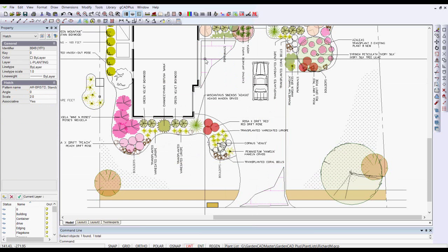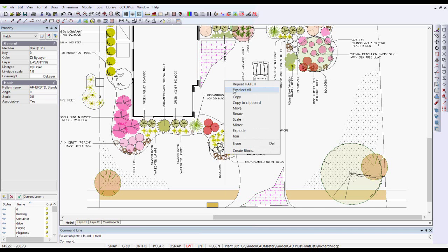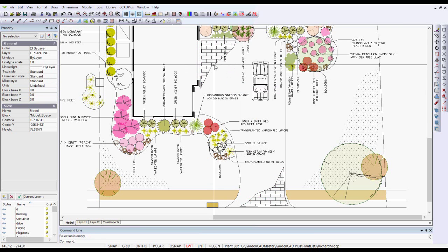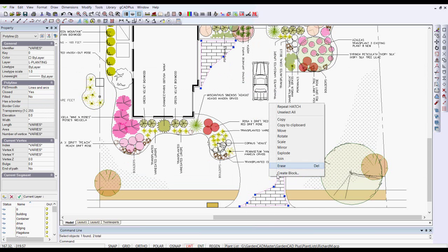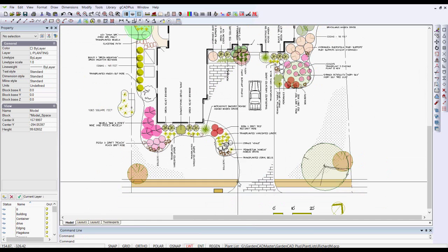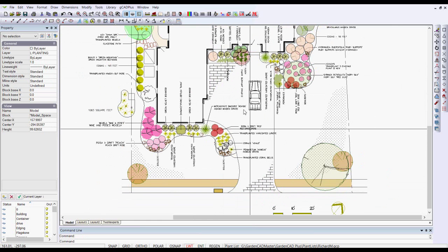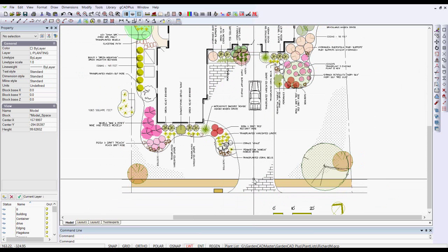and we'll go OK. Clearly that scale is a little broad, and so I can come over here into the properties box and I'll drop back to 0.5 and unselect all. So now we have our hatch pattern in place, and again I'm going to erase that zone through there. So for mine, clearly that's going to be a brick paved area now. It's indicated as being brick paving, but it doesn't overwhelm.